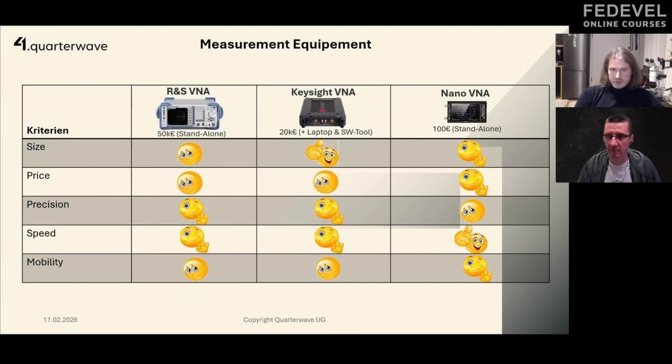And there are very cheap measurement devices like the NanoVNA. It's very affordable, 100 euro, 200 euro, and you can measure S parameters. I think there are versions up to 3 gigahertz, about 160 euro at Amazon, I looked last time. And that's enough here. So only a standard Bluetooth or Wi-Fi antenna you can measure or tune with this. Yes.